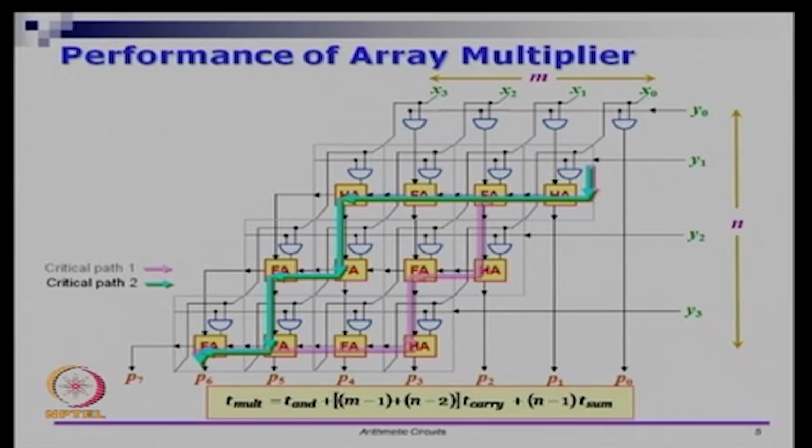The array multiplication is taking a number of steps which is not m times n, because you can generate the partial products in parallel and you can add numbers together. The array multiplication does not require mn steps, it requires order of m plus n steps.